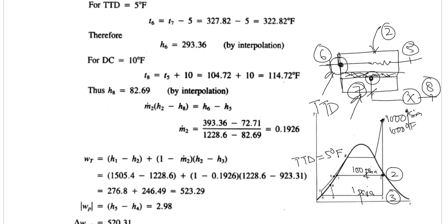It will reduce the temperature of the condensate, although it will not change the phase of the condensate, only the temperature, and the temperature of the condensate will reduce from 7 to 8 actually. Once we have got to 8, we can proceed to the throttling, and from 8 to 9 there will be a throttling, in which the pressure would reduce.